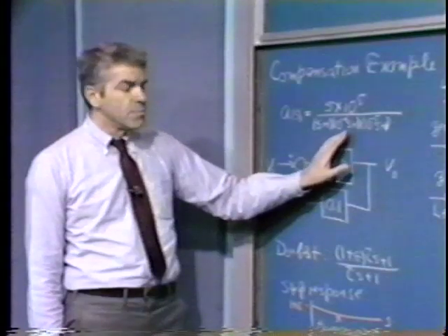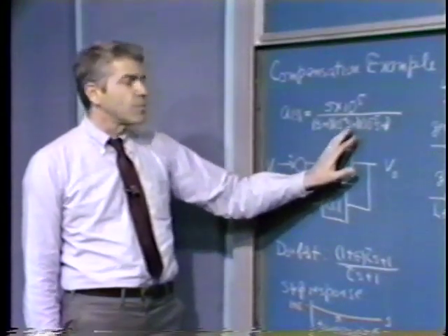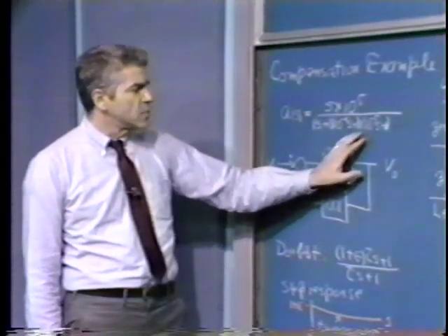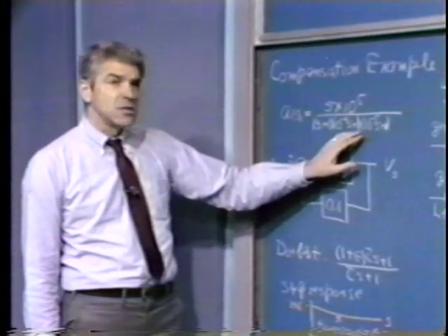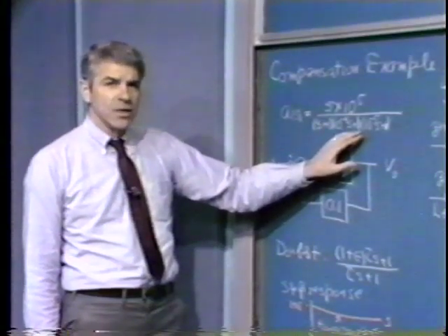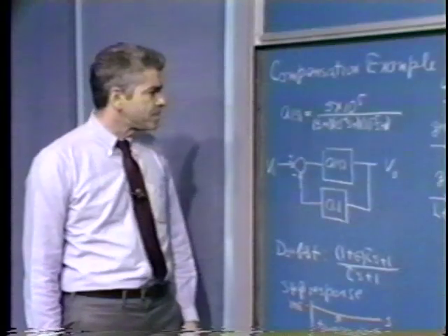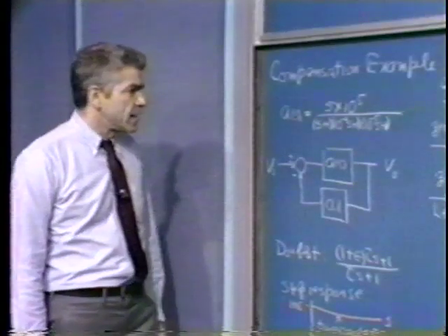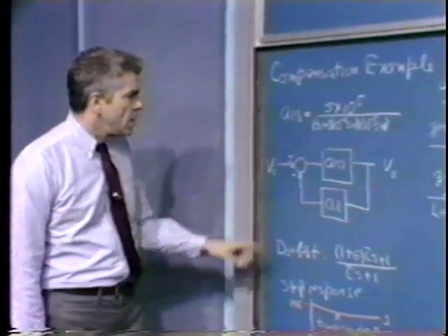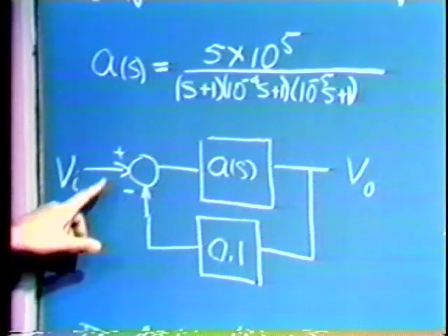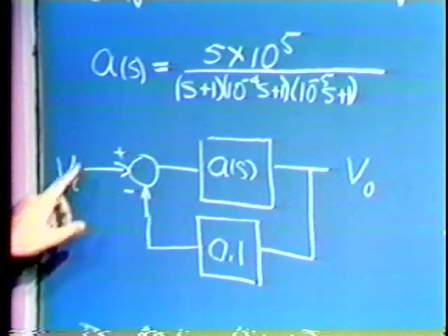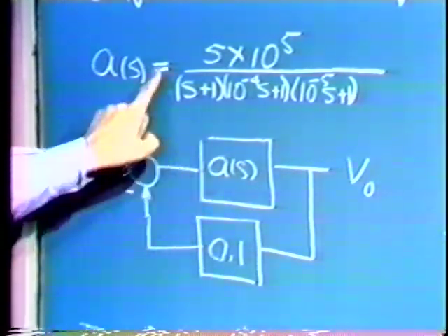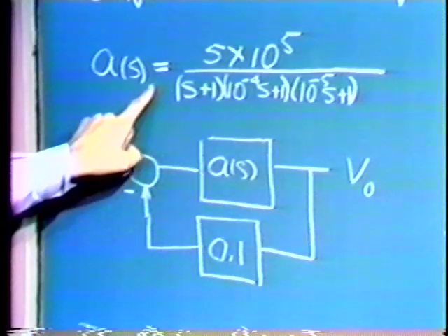So in order to be able to build a demonstration system that very accurately represents this equation, I've chosen to locate the higher frequency poles at a frequency that's considerably below the ultimate performance capabilities of modern operational amplifiers. If we take our operational amplifier and connect it in the non-inverting gain of 10 configuration, we get a loop that's indicated by the block diagram here. The input, the output, the open loop transfer function of the operational amplifier, the quantity that we've introduced earlier.